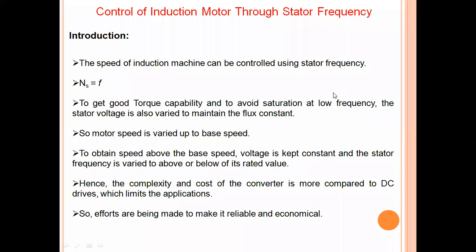Okay, before going to the main concept, we will discuss a few points about the introduction and the importance of frequency in the control of speed or torque. Generally, the speed of an AC machine, either synchronous machine or induction machine, is related to the stator, we can call it the supply frequency. Therefore, the supply frequency of the drive is varied if the speed of the machine is to be changed.